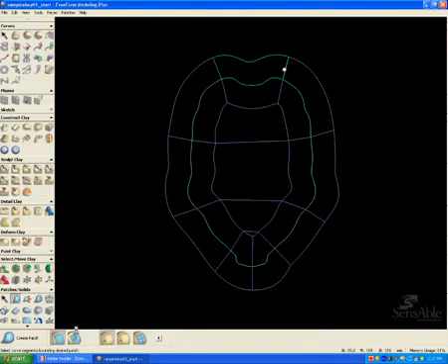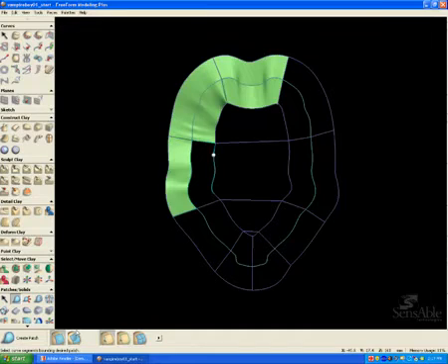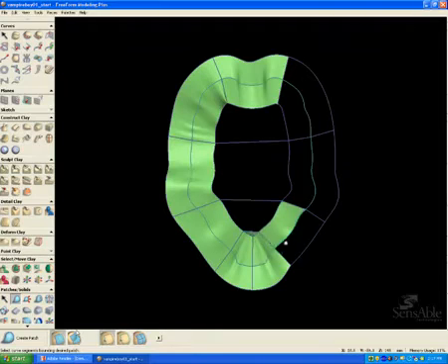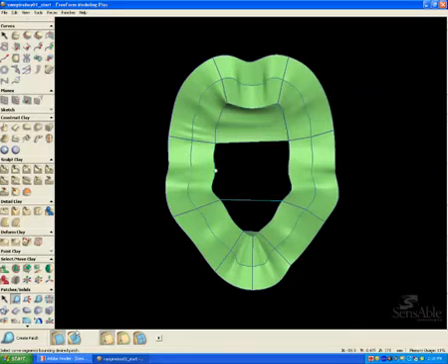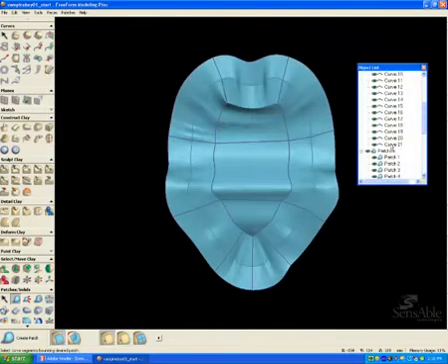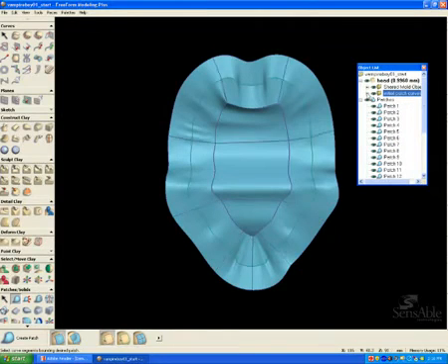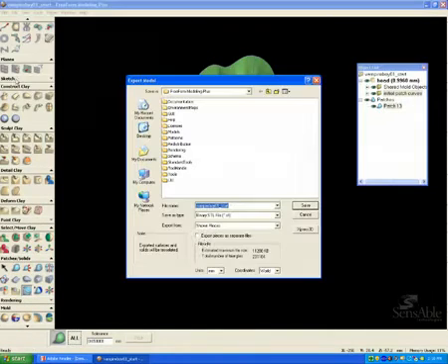And the reason I'm doing this is because I'm going to create this patch and then use it to create clay so that I can overlay a complex parting surface over that clay and then make a complex mold for the entire part. So as you can see, I'm making these individual patches using the curve networks that I set up. And from here in my object window, I'm organizing my lists, and I can take all of these individual patches and stitch them all into one patch.